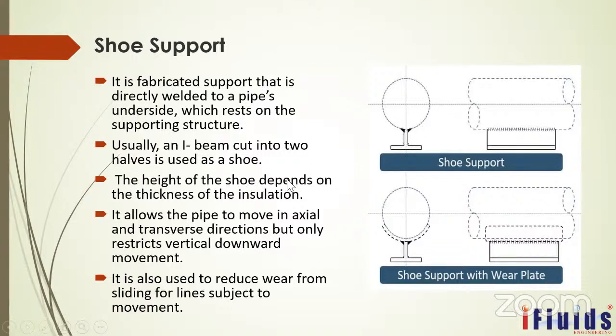The height of the shoe depends on the thickness of the insulation. Yes, this is the height of the shoe. The insulation thickness varies based on the temperature. If it is 50 mm or 100 mm, accordingly this height also will vary. So you cannot directly rest the insulated pipes on the secondary supporting structure. For those kinds of areas, we need these kinds of shoe supports.